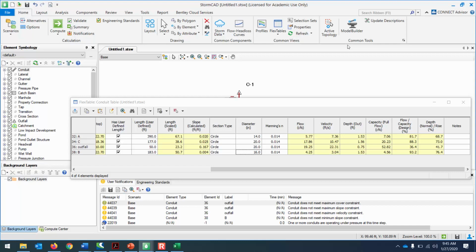If it turned out that one of your pipes is just barely over capacity, one way to give it more capacity is to raise the upstream end of it so that you've made it steeper. So maybe most of your boxes have a 5-foot depth, but this other one is only 4.5 feet, so that you've now made the pipe steeper and the pipe diameter doesn't have to be increased.